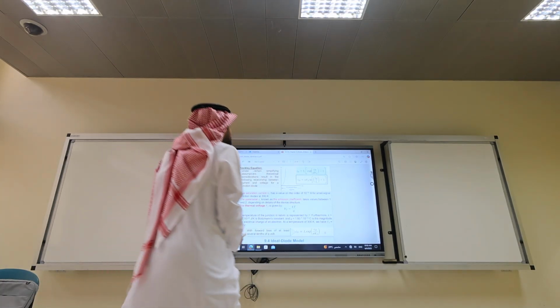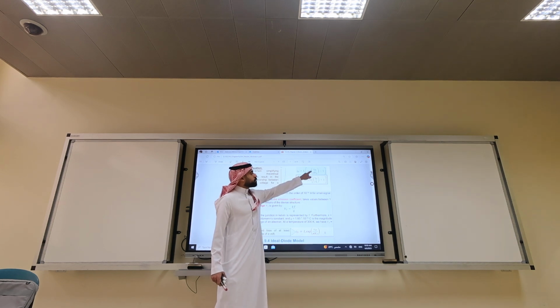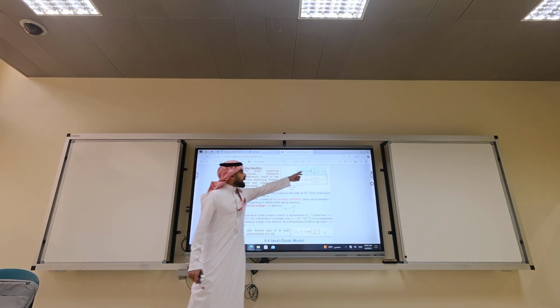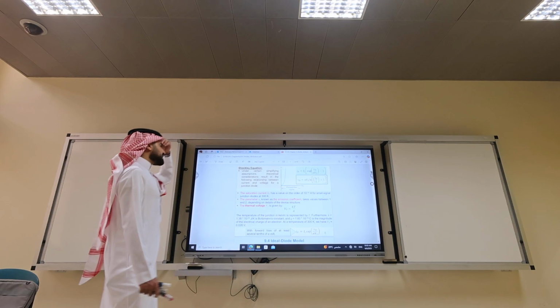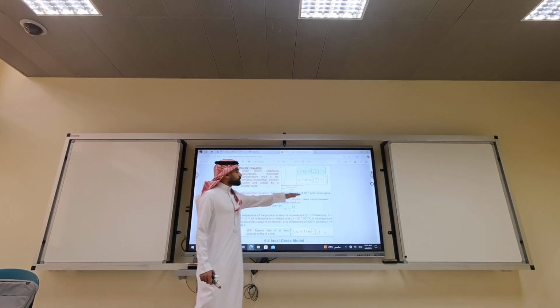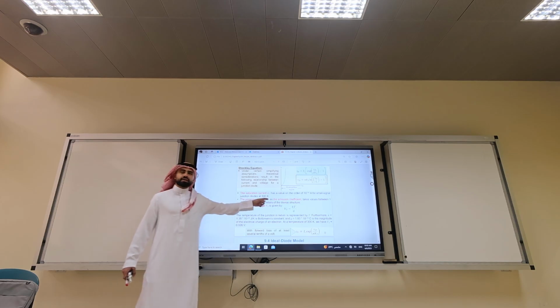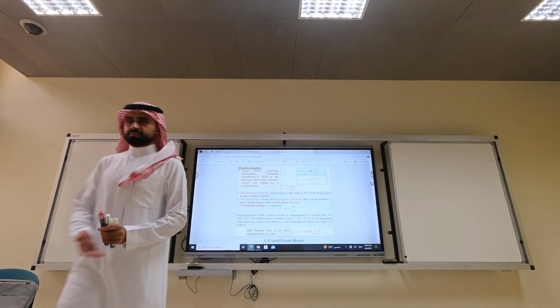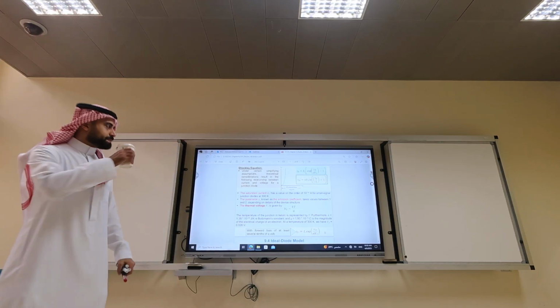And the equation consists of the expression IS times exponential of VD over NVT minus 1. Okay? So what is IS? IS is what we call the saturation current. Saturation current has a value in the order of 10 to minus 14 for a small signal junction diode at 300 Kelvin. How many degrees Celsius is 300 Kelvin? Somewhere around 25, okay?